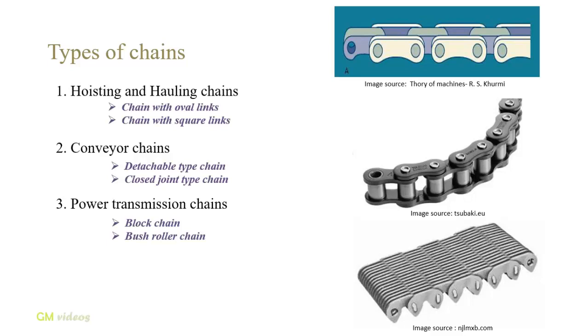However, elongation of links due to wear, and stretching of the parts, leads to unequal distribution of load on the sprocket teeth. This aggravates the wear of the roller surfaces and of the sprocket wheel teeth. The third figure depicts an inverted tooth, or silent chain. This chain is designed to eliminate the evil effects caused by stretching, and also to operate noiselessly. When properly lubricated, this chain gives durable service, and runs very smoothly and quietly.